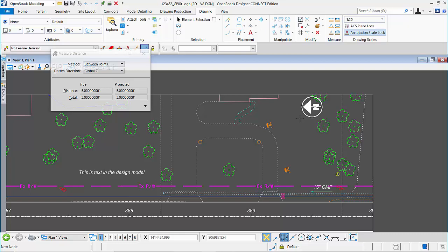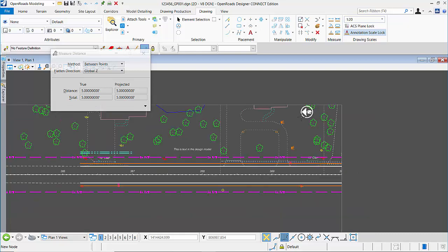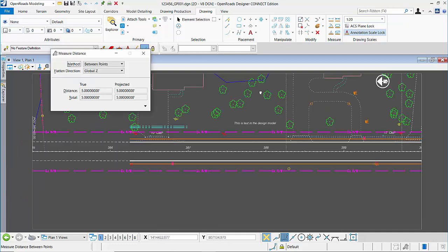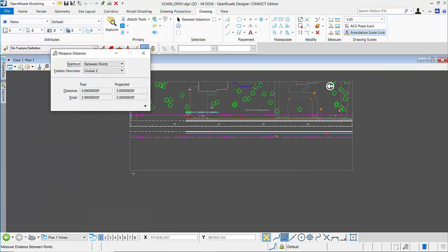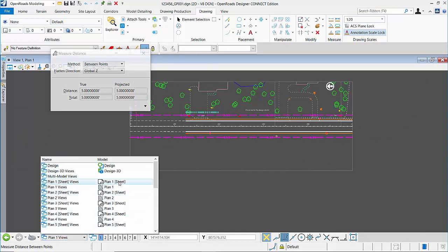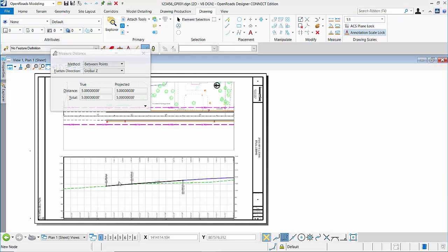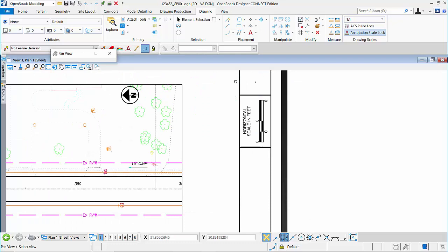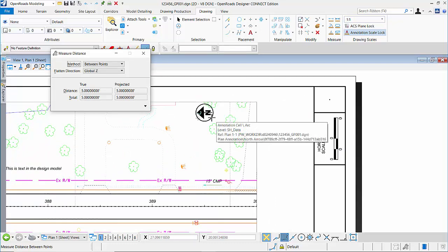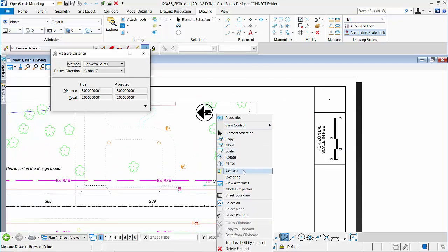Another thing to note is the north arrow placement. The software does allow annotation of a north arrow, but that annotation is relative to the alignment. So it's a distance along and an offset from. So in this particular release and probably moving forward, that's just going to be something that's going to be a change that's going to be located there. Now we still have the area in our sheet for the north arrow. So if you wanted to, you could right click on that, activate that,